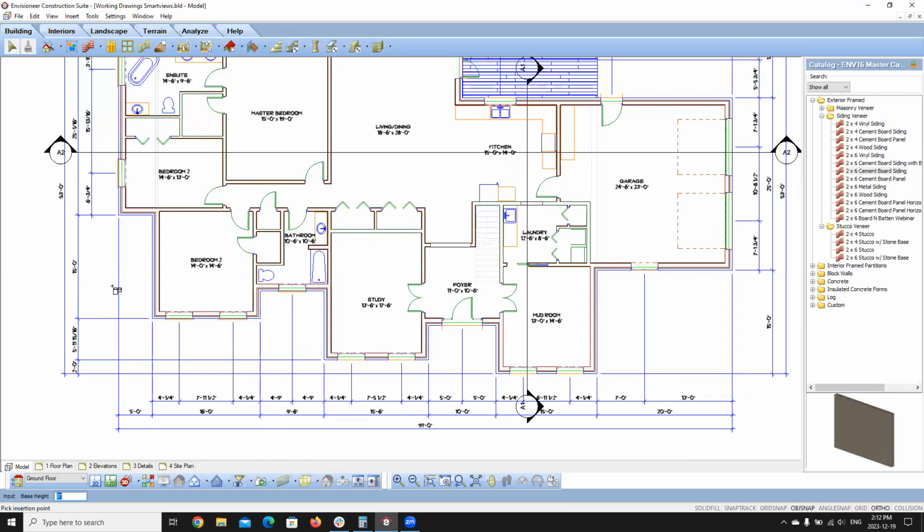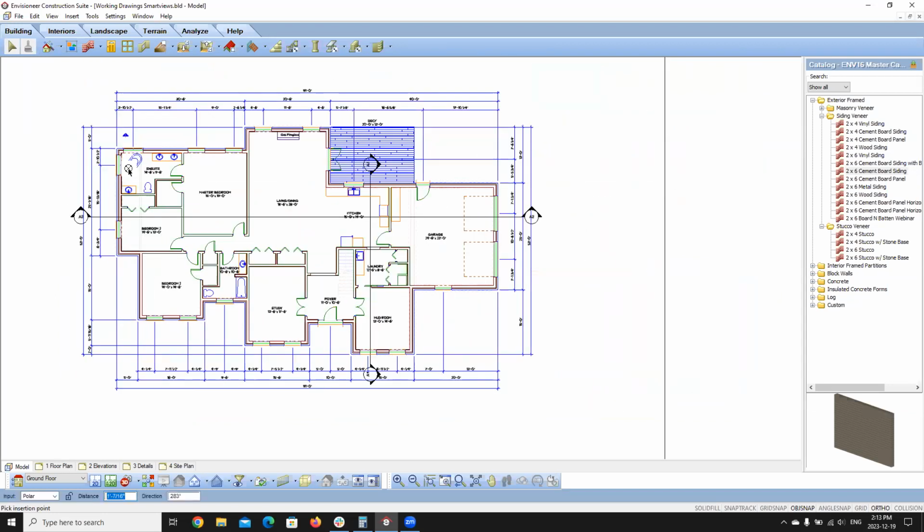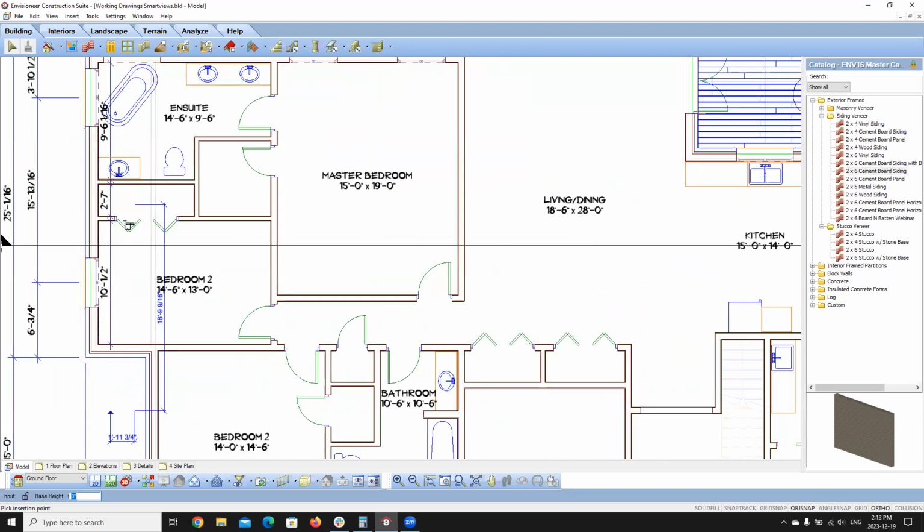So since we don't know exactly where your walls are or where you want your dimension strings to run, we give you the ability to create a line through your model, and then you can show where you want those dimension strings to be. I always start from the extreme, so I go from the outside to the outside, and I just left click to insert them. So now it's going to show me the thicknesses or the widths of each room from surface to surface.